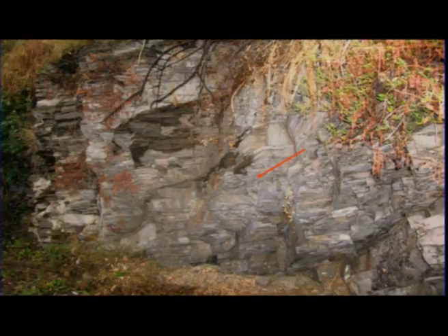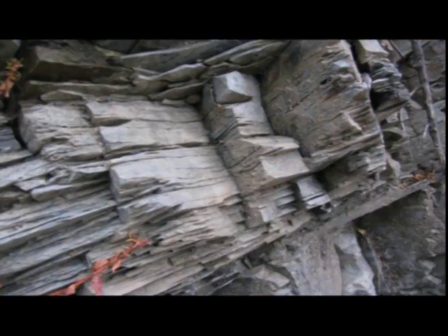Now, this is an example from the Himalayas, where the beds are dipping away from the screen. If you come across such beds, you can see that they are dipping; these are the bedding planes. Here, this will be your strike. Strike will be away from us, and then the inclination will be in this direction. So this is your dip direction, and this is your strike direction.